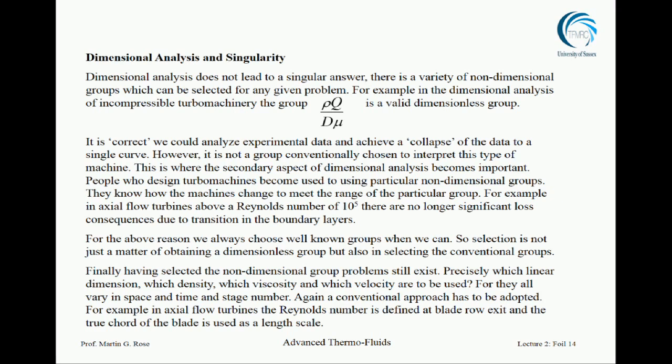So a good example is if you take an LP turbine from an aero engine and you monitor its Reynolds number when the aircraft is taking off. Inside the engine, the pressure is very high because atmospheric pressure is factored up by the compressors by a pressure ratio of about 40 or so. That air expands through two turbines, then gets to the LP. The pressure is still relatively high.